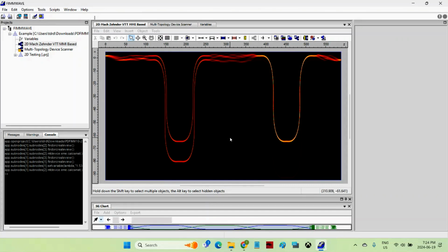So once we've done the design work, we have the ability to export to GDS2 file using just the toolbar button for easy mask manufacture. So not only does MT-FIMMPROP bring EME to the simulation of whole photonic integrated circuits, but it also combines the roles of both simulation and layout tools for convenience.